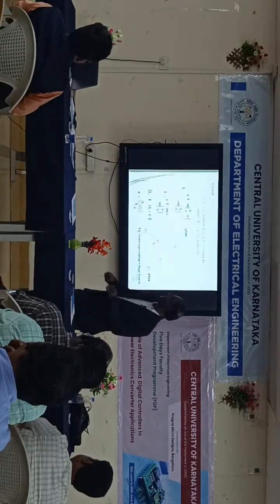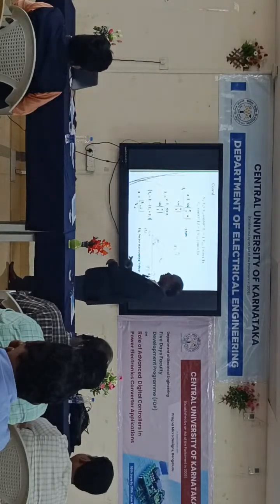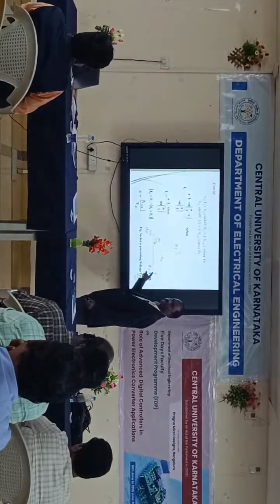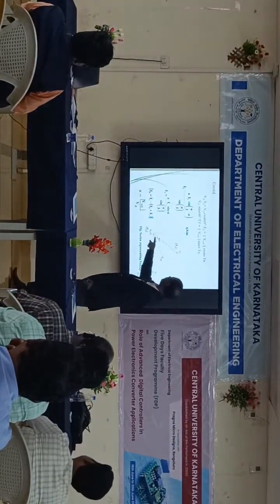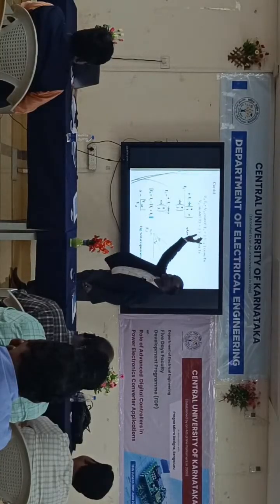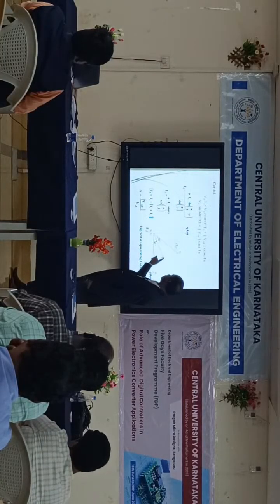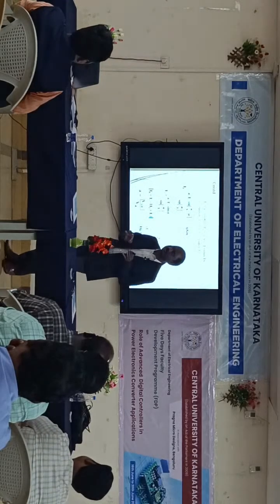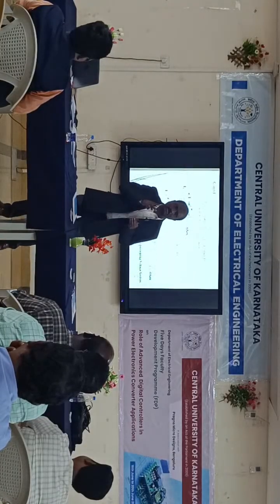Okay, so Ts is this. And similarly sin 60. What is the sin 60 of this one? The vertical component of V2 is Vd sin 60 for a period of T2. And also what is this one? V reference into sin alpha for a period of Ts. So this is the volt-time balance. We have two equations.